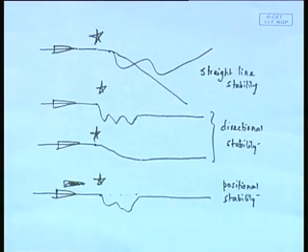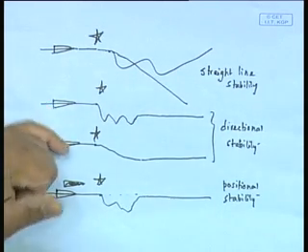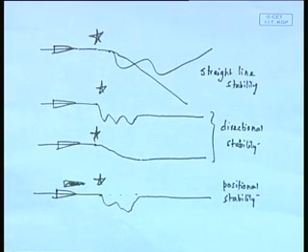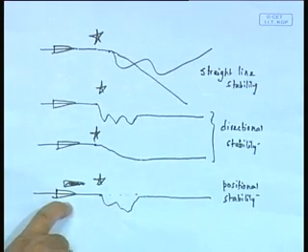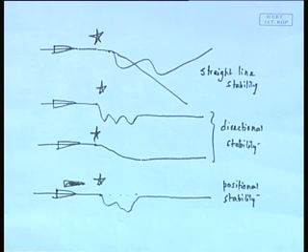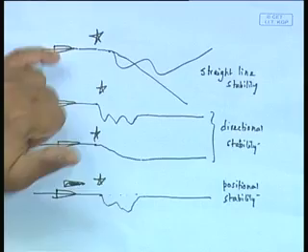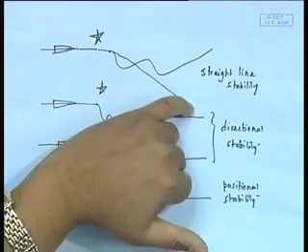Now, the interesting point is that none of these three are ever possible without an external force like rudder action. In fact, this is not even possible without having a controlled rudder action. You must have an appropriate controller. As far as only hull is concerned, that is, you do not apply the rudder, you can only have this characteristic.